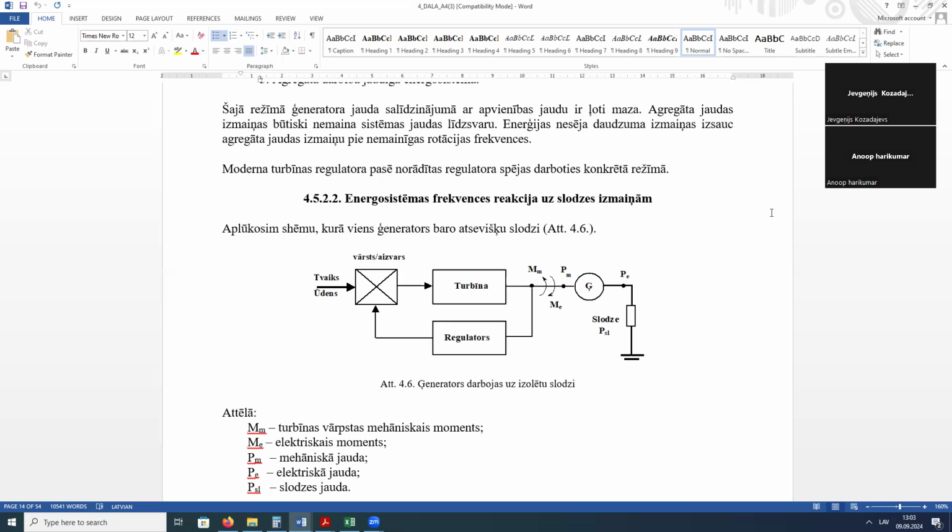For example, if we have a network with only renewable sources of energy, it means that we produce DC, we have inverters to convert it to the AC, and inverters push energy to the network. An inverter is not a rotating piece of metal. It means that it doesn't have any inertia. In this case, all the changes in the power network go very fast, and we don't have any time to make actions.